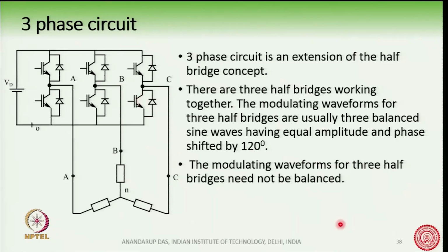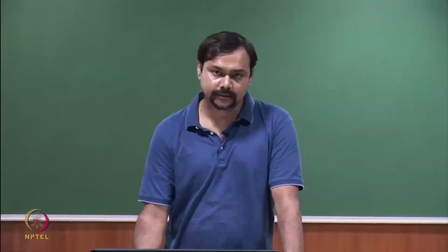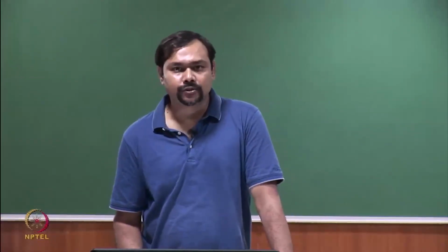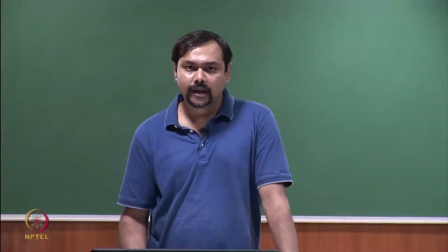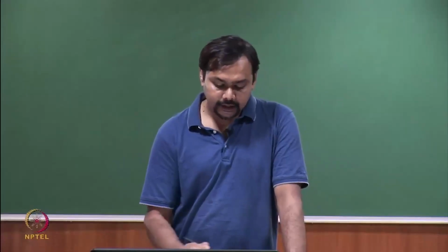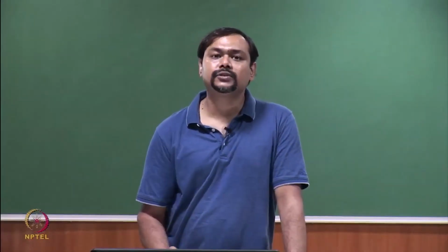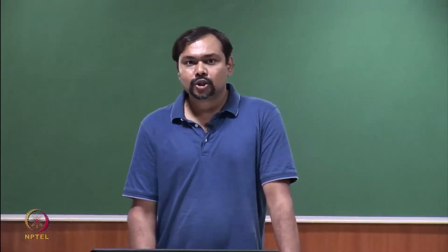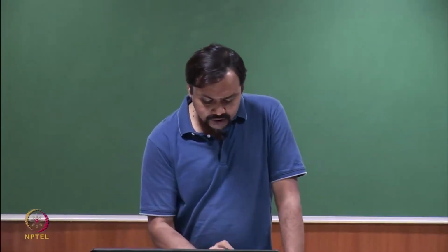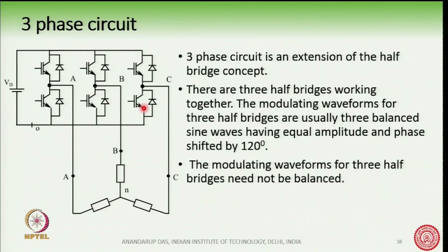Okay. There is no requirement that these 3 waveforms have to be balanced. They can be unbalanced also. In fact, when such a converter is used in an unbalanced system, then it may be required to produce unbalanced voltage waveforms from this converter. So, these three half bridges usually operate with balanced reference waveforms, but they can also operate with unbalanced waveforms.